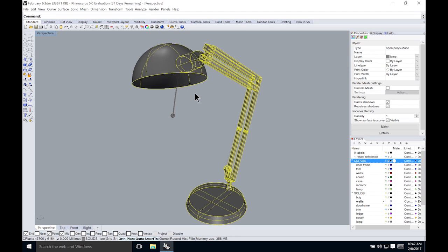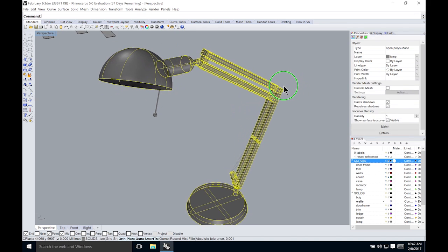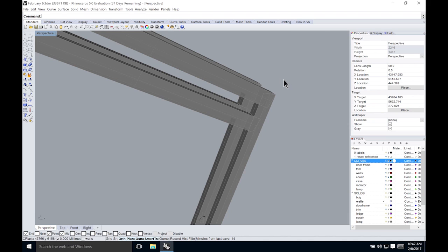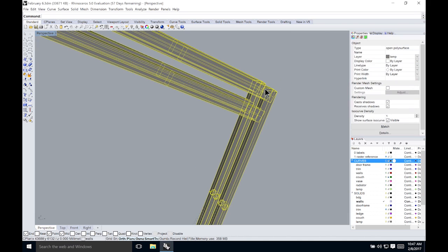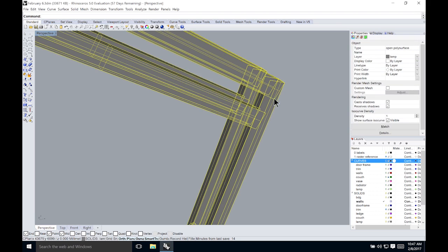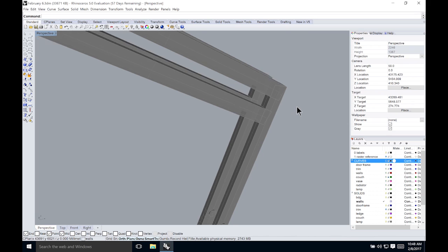I think the reason for that is that it was created from a solid. So sometimes it matters what the basis of the geometry is. If this was just a flat surface, then I don't think it would have worked to Boolean this together. What's nice now, and this relates to creating 2D drawings, is that after you join objects together with the Boolean operation, you can see that the original geometry of this corner intersecting in space with that is still visible.